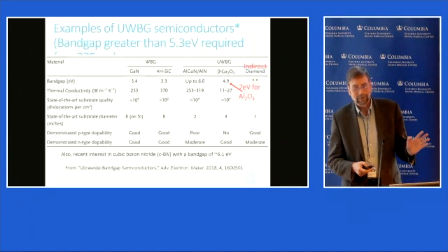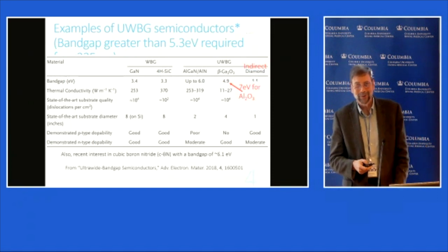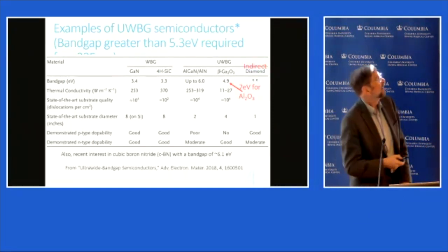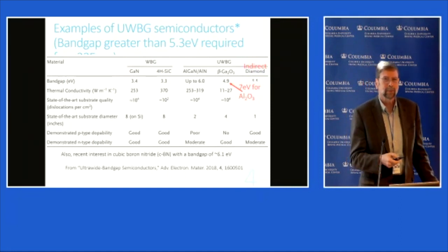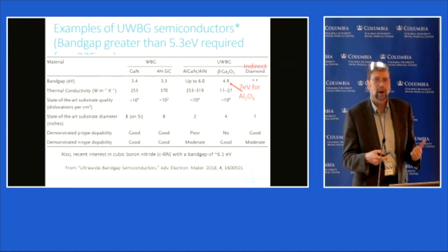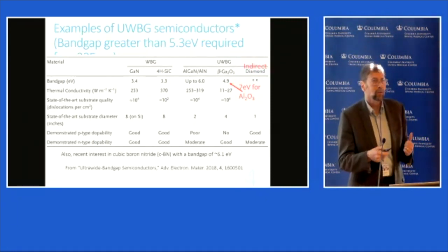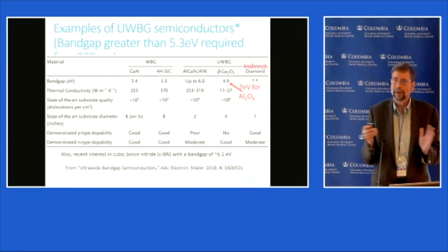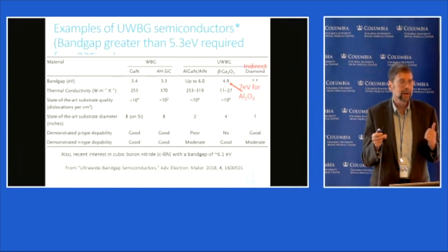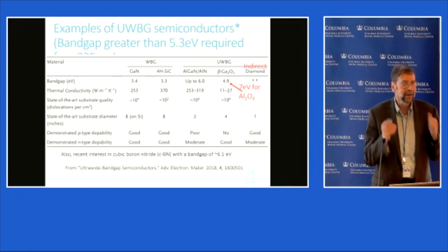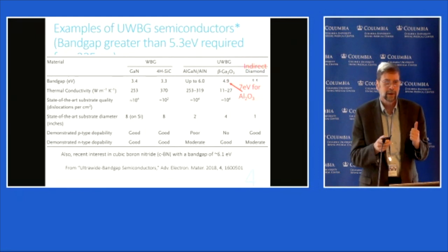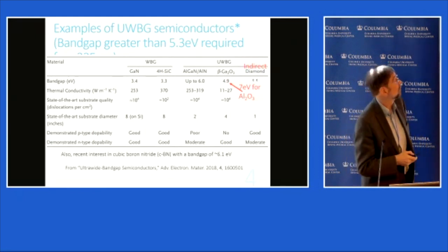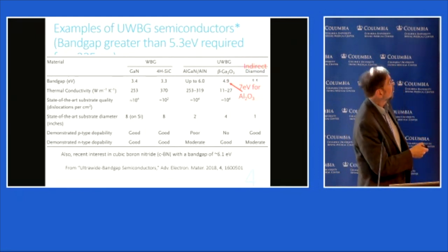There was also a question about semiconductors. I thought I'd put this slide in too, that just gives you a view of wide band gaps and ultra wide band gap semiconductors. So this falls in the category of ultra wide band gap semiconductors. I know there are people with many different backgrounds here, but one of the points I'd make is these are what I grew up calling insulators. It's very difficult to dope them. There's only special materials that it's been possible to dope. The AlGaN system is one of them. Boron nitride is another one that's